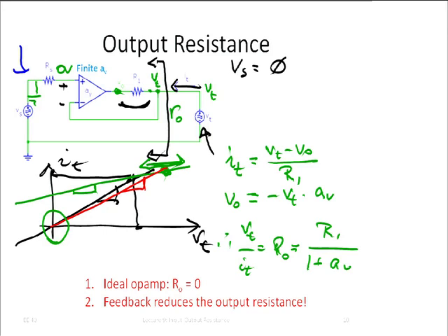well, this amplifier is in what kind of configuration? It's unity gain, right? It's a non-inverting amplifier, and it's simply the output is tied back to the negative input, so the gain is 1. We can see that easily. If now the gain is large, right, then this voltage here, I marked it already, this voltage is 0, so the input Vs and the output Vout, they're equal, right?